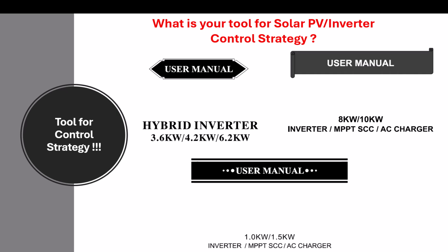So if you connect a motor, for example, you connect a pump, which is an inductive load, then you have a failure of this inverter. Then you say, no, my inverter is not strong. But in the user manual, it gives you the boundaries of what an inverter can support. Similarly, with a battery, it will give you all the boundaries of what it can support.